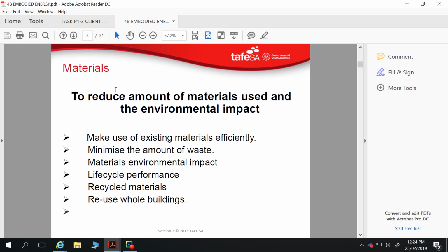What happens when you get a leaking bath or leaking shower? Well, actually, let's not talk about wet areas. That's a whole new can of worms. We'll talk about water damage from something else, like some water making it into your walls from bad fascia, and that particle board swells up because it's underneath your walls. You can't just easily replace that bit.